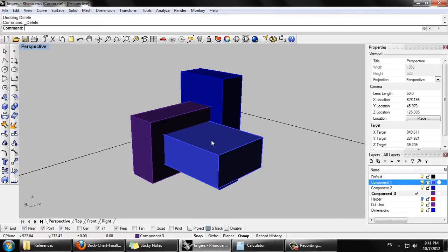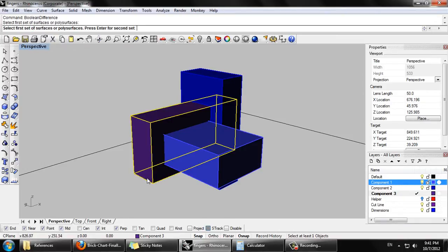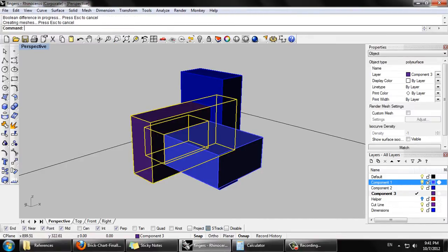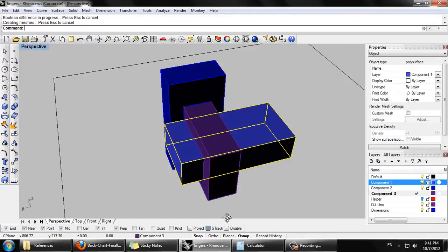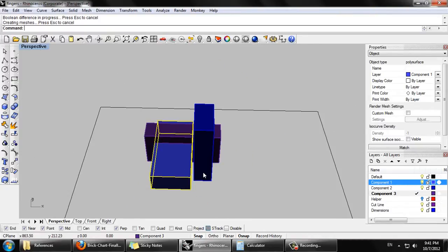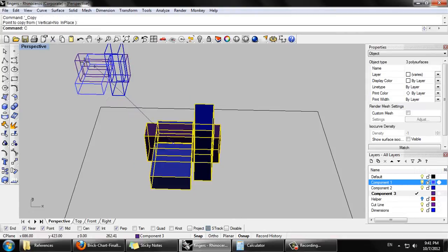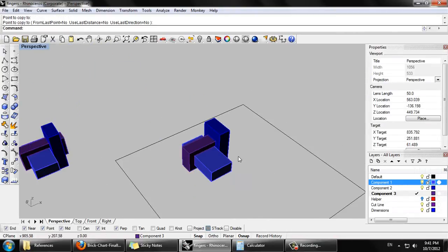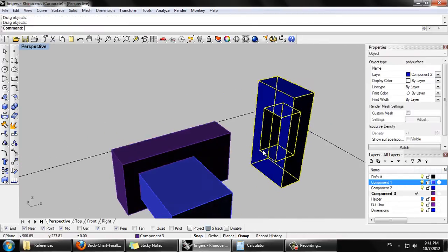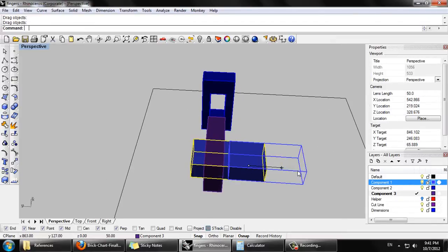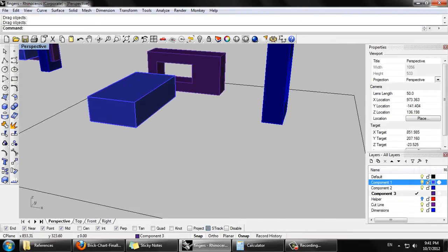And we can directly do Boolean subtract for this, or Boolean difference. And delete input to no. So here we have the updated volume. Okay. So we can copy this aside for the moment, and separate these volumes so we can see what we're working with.